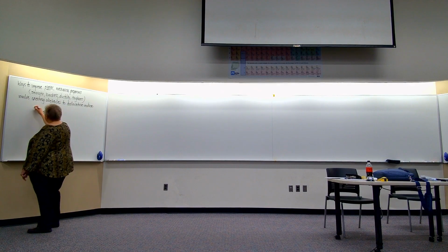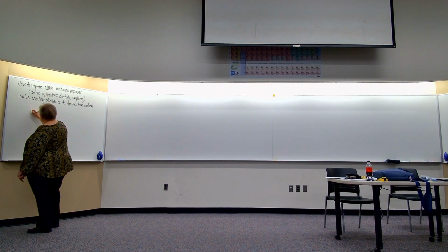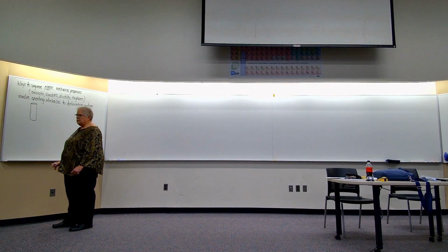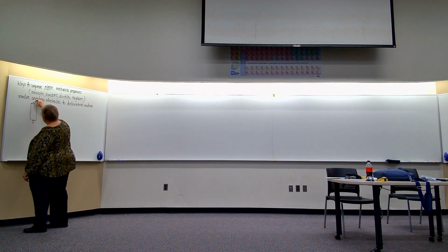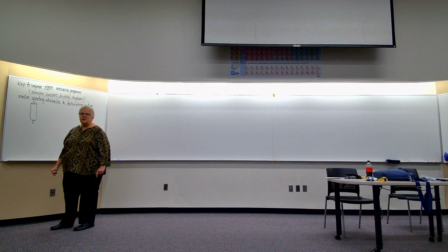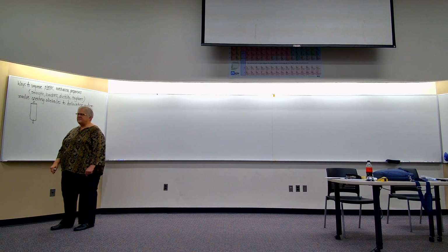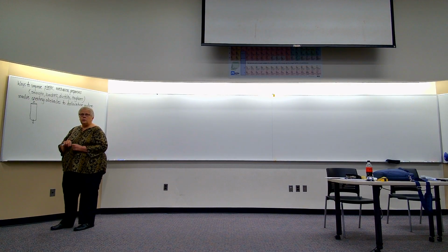So maybe one new illustration of that would be, I'm not going to put in reduced cross sections because it makes a more complicated image, but if I pulled on this, the way that it gets longer is not bonds breaking in the direction of stress. The way it gets longer is by planes of atoms sliding past one another because of dislocations.